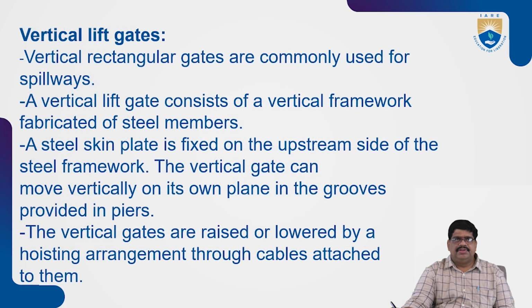Next, vertical lift gates. Why vertical lift gates? Vertical rectangular gates are commonly used for spillways. A vertical lift gate consists of a vertical framework fabricated of steel members. A steel skin plate is provided on the upstream side of the steel frame.